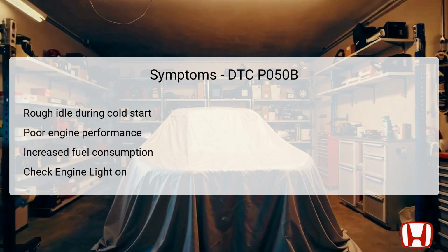Additionally, fuel consumption tends to increase as the engine struggles to maintain efficiency, leading to greater emissions as well. Finally, the check engine light, CEL, is typically illuminated, alerting the driver to a malfunction that needs attention. Recognizing these symptoms can help guide timely diagnostics, preventing long-term engine damage.